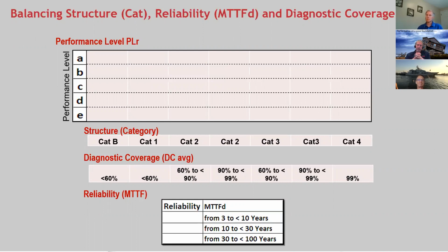And that particular risk assessment methodology basically said, well, we're going to use the severity, our frequency of exposure, and our ability to avoid the hazard, and we're going to go down that tree, if you can picture it in your mind, and we're going to come to a place where a risk level is going to be identified, and that risk level is going to directly tie into what we need to do to mitigate that risk. And if it has electrical